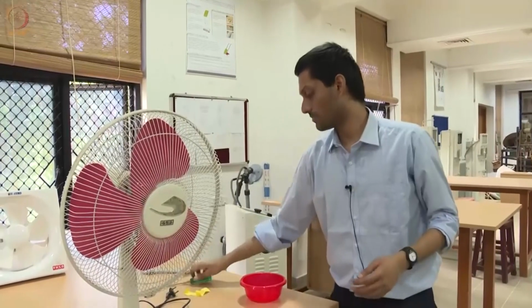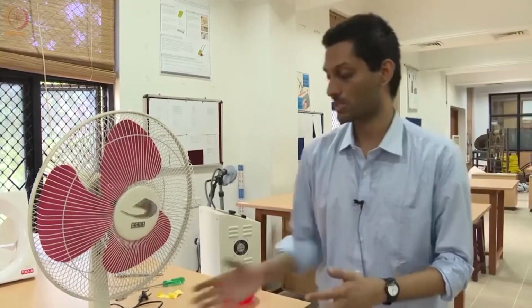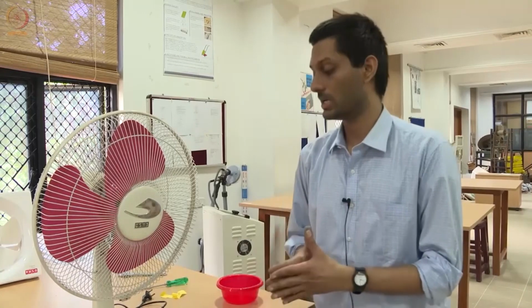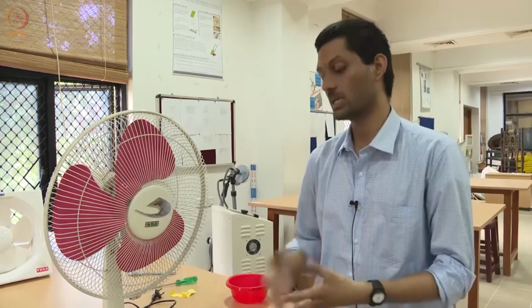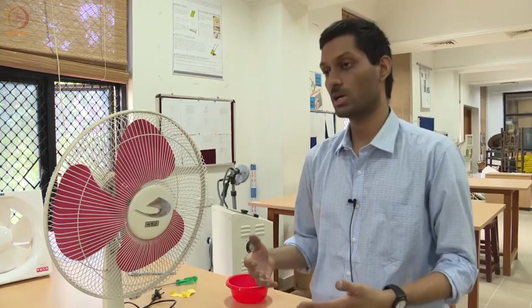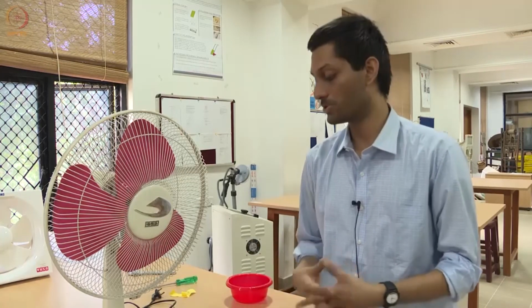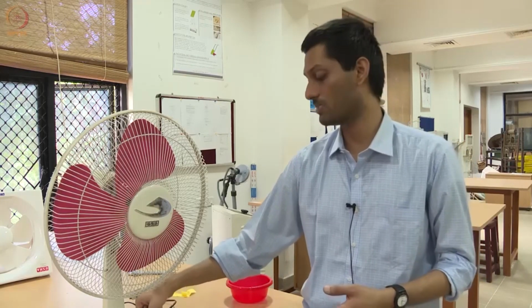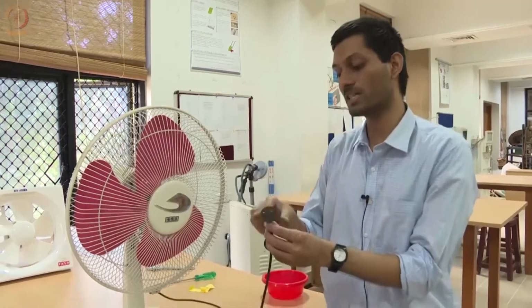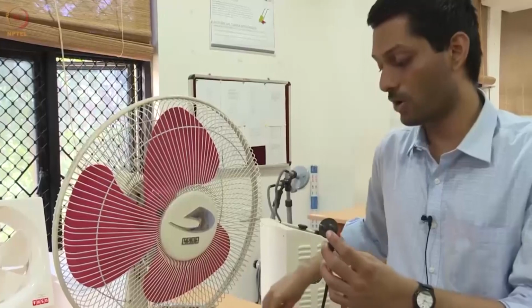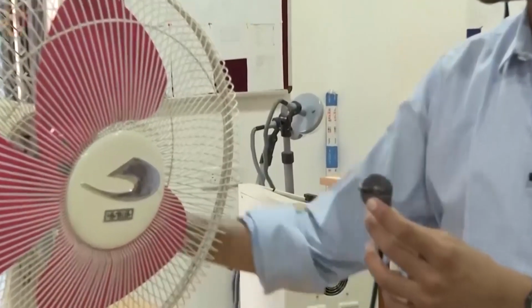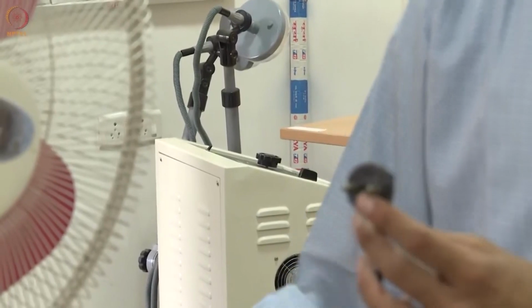Another thing which I should mention is the electrical connections, because whenever you dismantle any electrical product, first you should unplug the device, and the most important thing is to pay attention to the wires that are inside the system. If you are removing any of the insulation, make sure it doesn't accidentally touch the body of the fan. In this case, the body of the fan is made of metal, which means it can become electrically conductive. Also you can see there is no earthing pin on this fan, which means if for some reason any of the insulation breaks down, the entire body of the fan can become live. So that's a safety hazard.